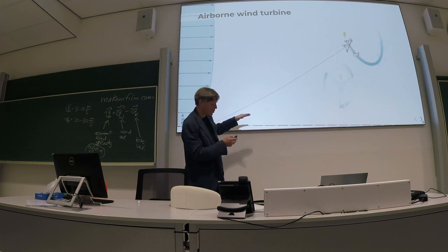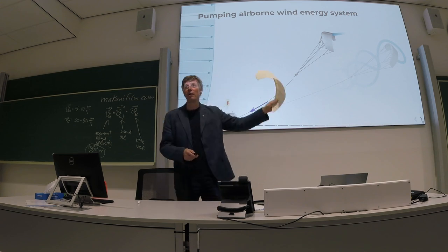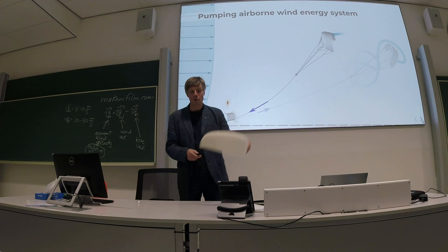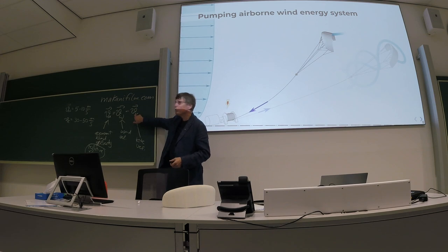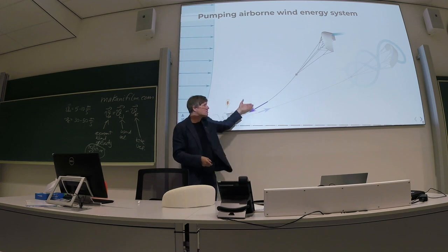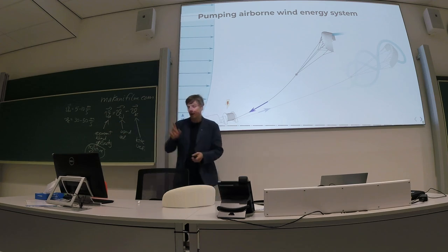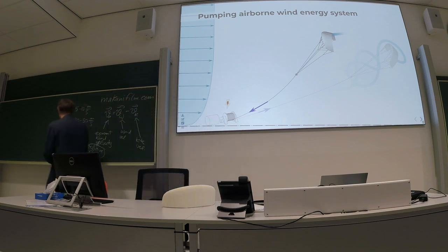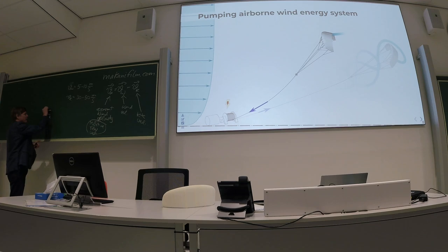Then to fly back, we stop these maneuvers. We basically park the kite in the air. We stop it from moving. You see it already from this equation that between reel out with fast crosswind maneuvers, and reel in with the kite velocity dropping to just the reel-in speed, makes a big difference on this VA. And maybe one additional formula to start. This VA has an important effect on the aerodynamic forces.